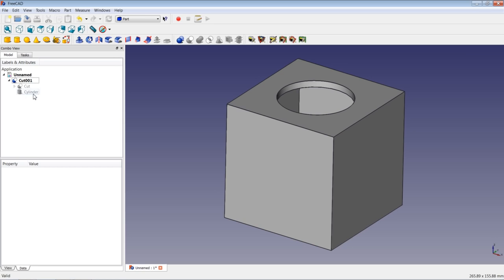Here I chose the cylinder to be of the same height as the box, which is not every time a very good idea when performing Boolean operations. It could be successful, but there are some occasions when you have coplanar faces that the Boolean operation will fail. So it is often a better idea to have overlapping shapes when performing Boolean operations.